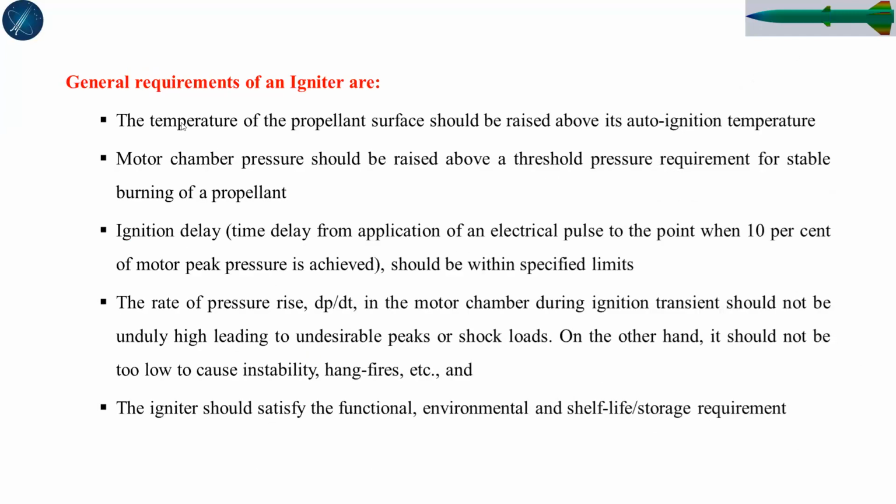Still, the general requirements of an igniter: the temperature of the propellant surface should be raised above its auto-ignition temperature. Motor chamber pressure should be raised above the threshold pressure requirement for suitable burning. Ignition delay time is the time from application of an electrical pulse to the point where 10% of motor peak pressure is achieved, so igniters must provide about 10% of the motor peak pressure.